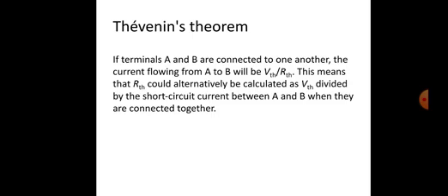This method is valid only for circuits with independent sources. If there are dependent sources in the circuit, another method must be used, such as connecting a test source across A and B and calculating the voltage across or current through the test source. As a Thevenin replacement, voltage and current sources can be remembered as the source values, meaning their voltage or current, are set to 0.